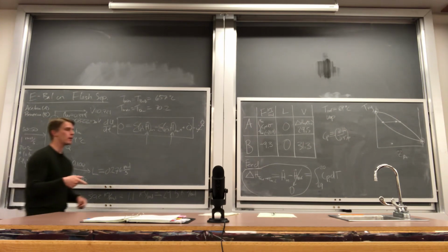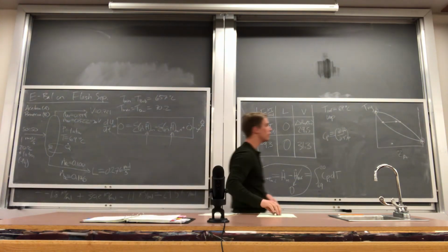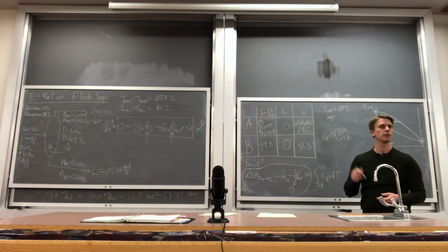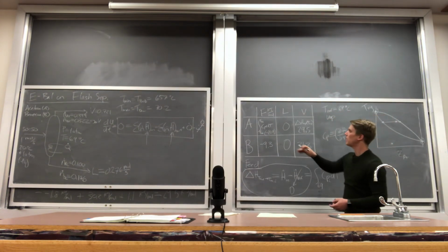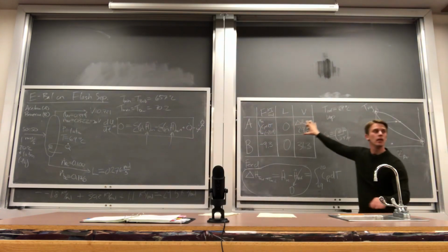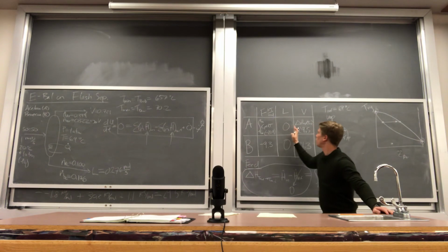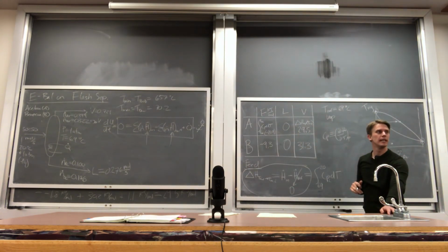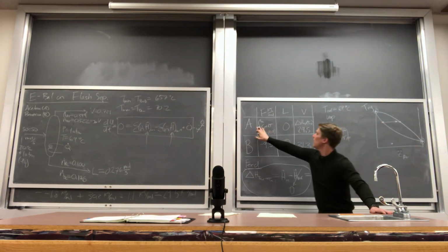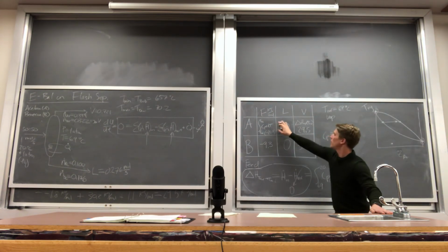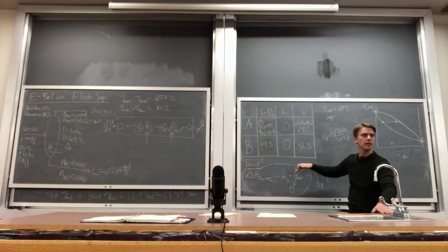So what I would really recommend doing if you were to solve this problem is to not do it by hand by any means possible. Do it on an Excel spreadsheet. When you build your big table where you're filling in your enthalpy values, add an extra column for the flow rates of each of the individual species. Because then you can do N of the feed times its enthalpy, N of the feed times its enthalpy added together, N of the liquid times the enthalpy of the liquid, and so on, added together.